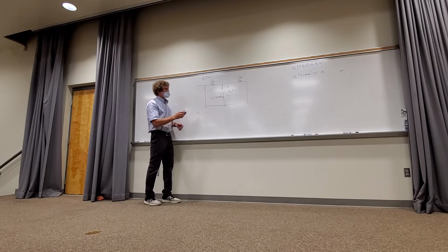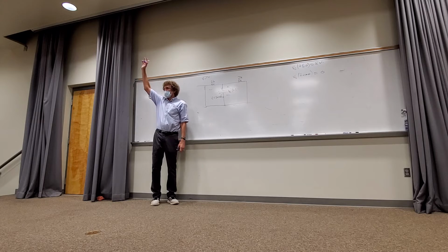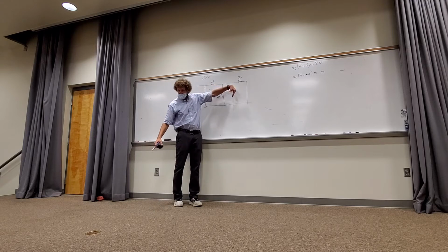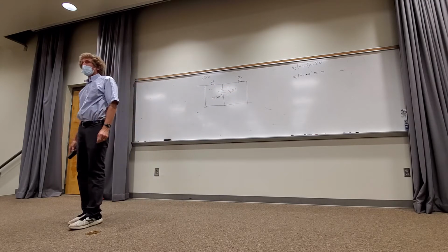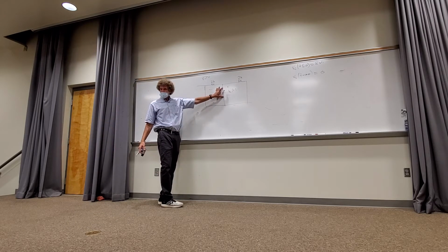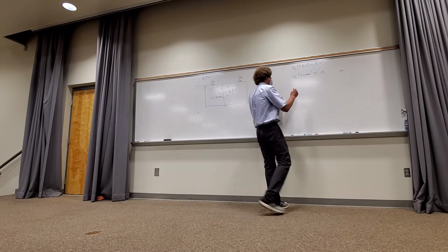Now, I hope you can see this by now. How many see that the 2K and 2K are in parallel? All right, by now you should see it, right? I could literally take that and bend it this way, and take this and bend it this way if it helps, but you all see that they have the same exact voltage across them. If you put a voltage here, it would be in parallel across both of those. You all see it? So if you look there, the R Thevenin would be 2K in parallel with 2K or 1K.